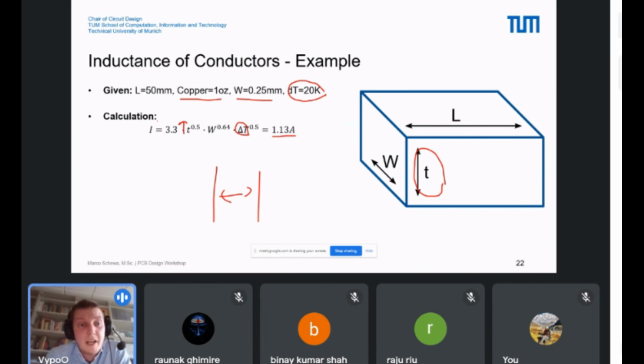One is something you have to keep in mind, because for example, KiCad doesn't know that the currents through the wire increase the temperature. This is something you have to calculate by hand or simulate with a higher performance tool. For example, Altium. Altium can also simulate the temperature on the wire.